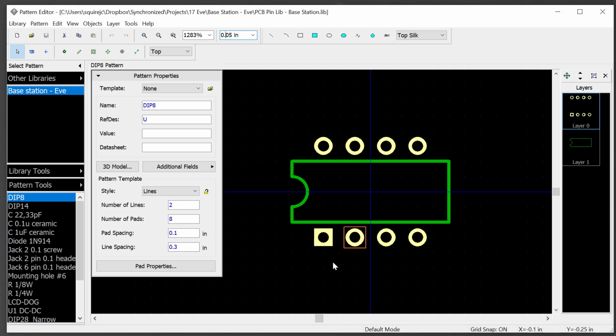For integrated circuits, you want to make sure that the grid goes in evenly into a 0.1 inch spacing, since the pins on a DIP are at 0.1 inch spacings. This is at 0.05, and sure enough you can see that these pads exist at every other location of the grid, so they're at 0.1 inch spacings. Let's take a look at another.